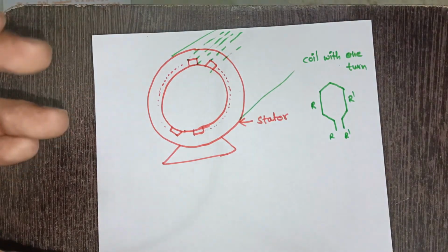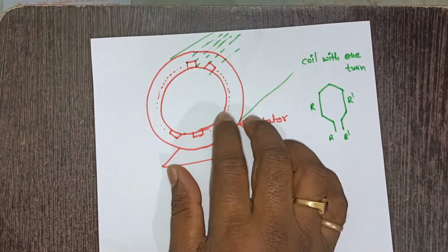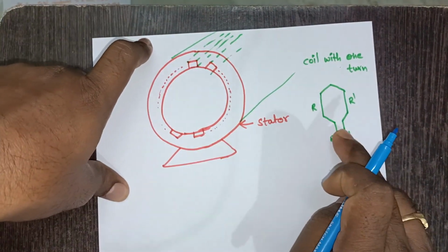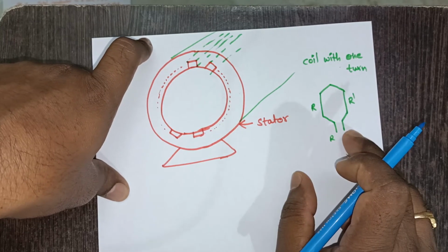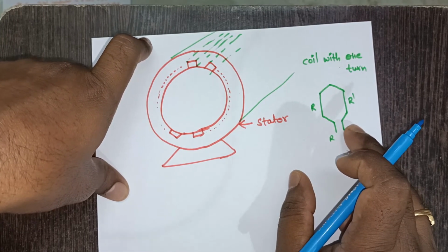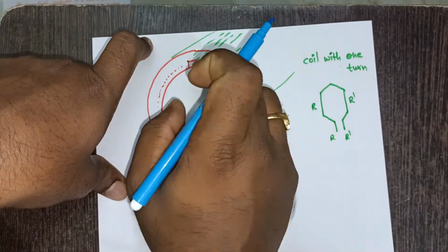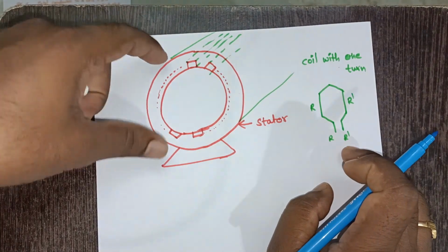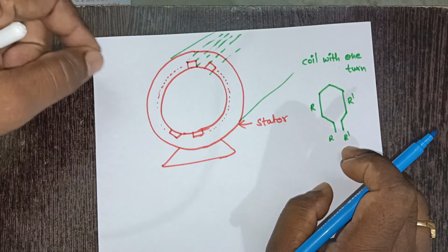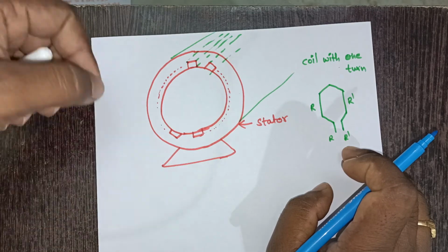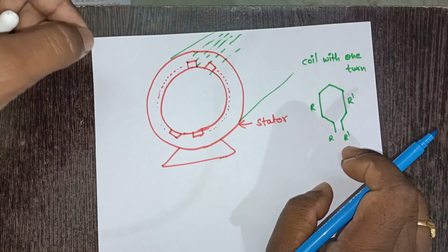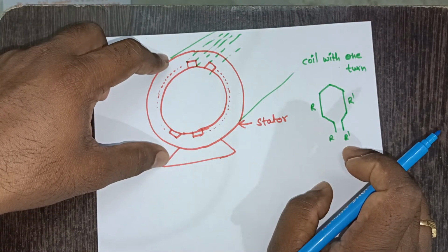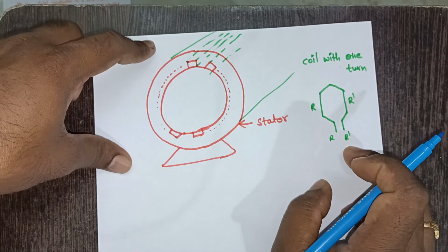So I am going with this two-dimensional view diagram, and in it I need to insert this phase winding. Let me take this as the R phase. Let me put one phase first, then analyze what happens when we give excitation to this phase. After that, we will put the other phases also, since we need to design a 3-phase winding. Before putting all 3 phases, we first put one phase and try to understand what happens exactly inside this machine after putting the phase winding and giving supply.